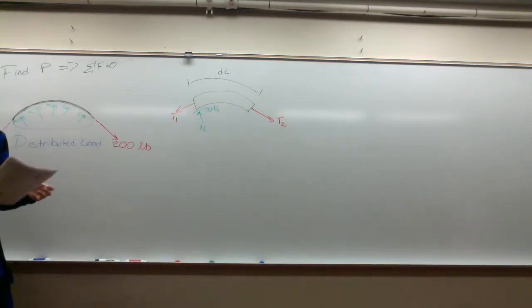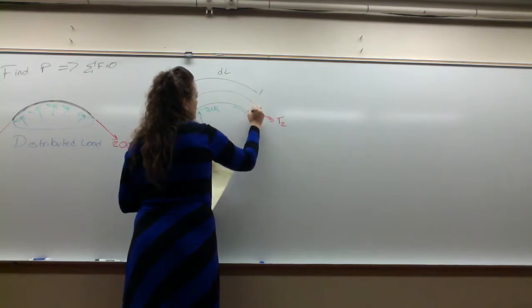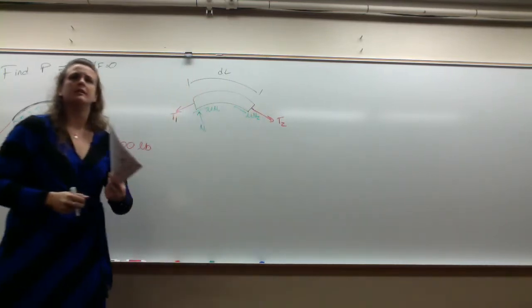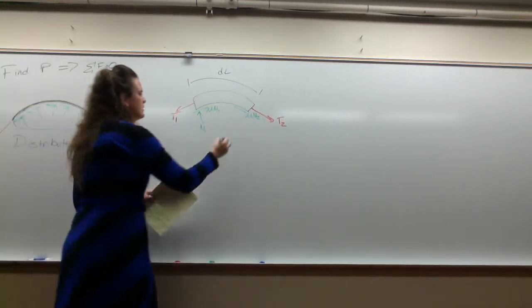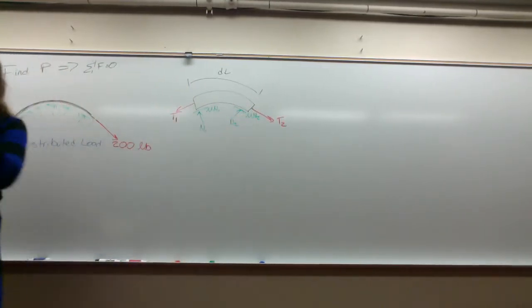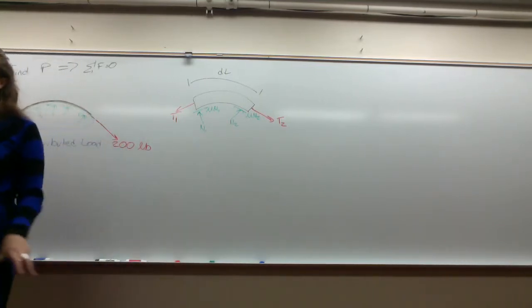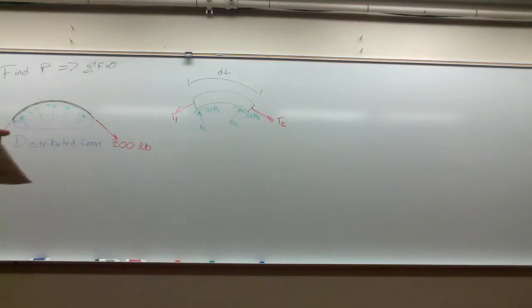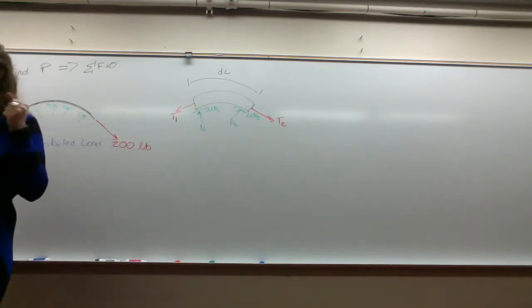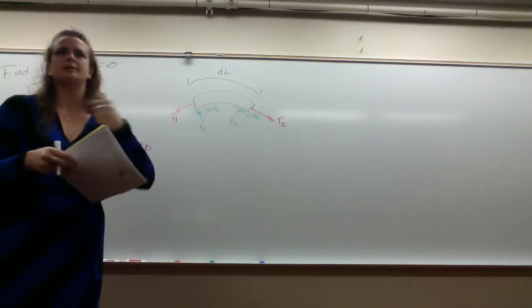We have another point of contact over here. We have our coefficient of friction and our normal force at this point, tension 2. That will indicate with the normal force 2. So we're infinitely small, and this is what we're integrating across. But the nice thing about pulleys is we don't have to integrate across the surface.